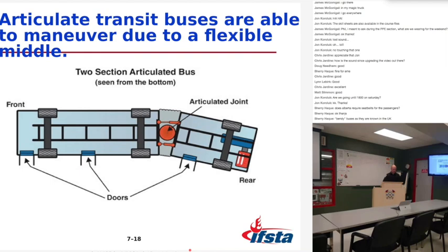Configuration can vary there. You can have a puller, two separate engines, one in the middle of the tractor, one in the rear of the trailer, or a pusher, a single engine in the rear of the trailer. Integral body construction, undercarriage structure, longitudinal beams that support horizontal and vertical beams made of carbon steel, mild steel, and other materials. Sounds like the undercarriage is tough too.